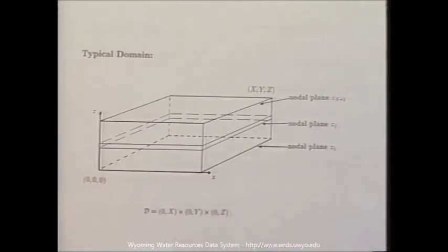It's rather hard to depict on here, but that's another possibility. Of course, the last possibility is a finite element method in 3 dimensions, which can get extremely large. The whole idea of this particular method is to incorporate some of the nice facets of the Fourier series and the rapid solvers with a finite element to handle the varying layers.